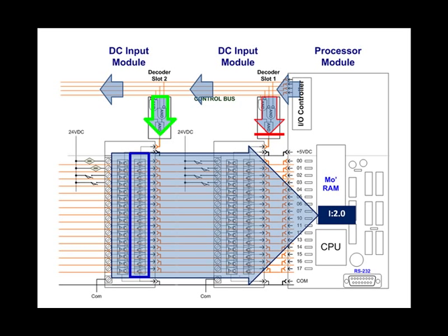Why not just hook all of the 16-bit cards, inputs and outputs, into a single data bus of 16 conductors going into one set of 16 screw terminals on the processor? Keep in mind, if we add some electronics to the processor, we can read in inputs into memory, and when it comes time to do the outputs, we can read those out of memory out to the cards. You'll see this in a bit. So we're going to plug all of the input and output circuit cards into the same backplane, common bus, and let the processor sort this all out.